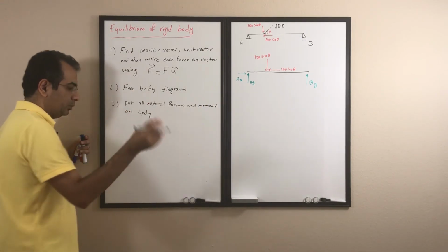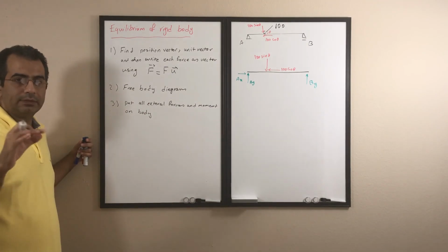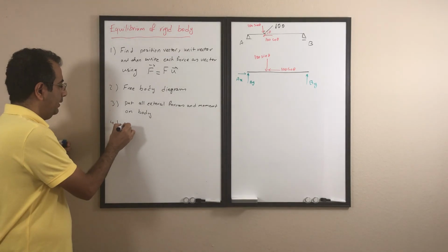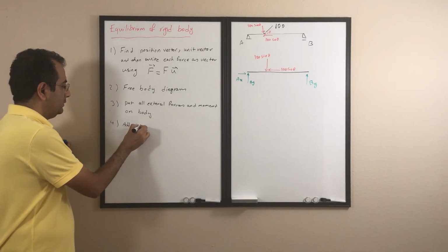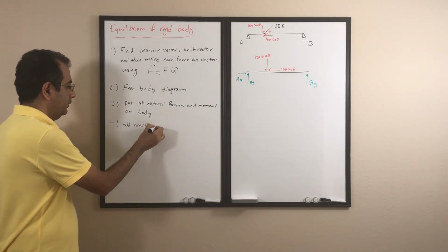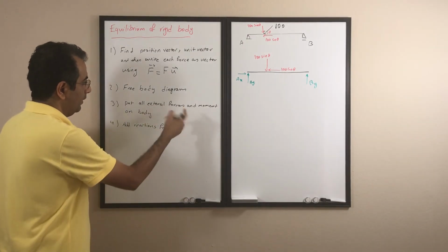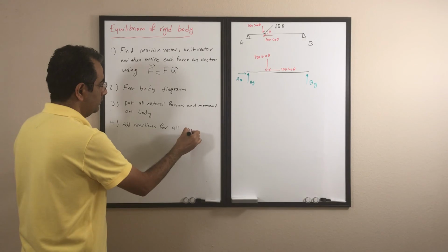So go back and put all the external moments and forces you have on the body. Then add reactions for all supports,